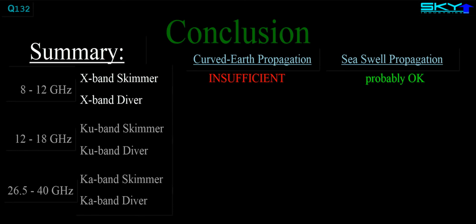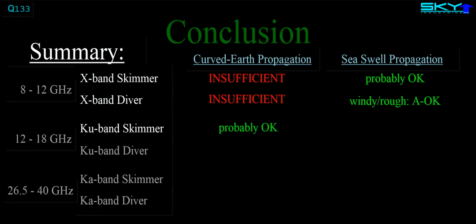If the sea is glassy and smooth, then forget it. A simple jog detector won't get you across the finish line, but if the sea surface is rough, you're good to go, most likely. KU band sea skimmer. A simple rate-based jog detector is probably okay, although the results are mixed if the sea surface isn't perfectly flat, like if there are sea swells, of which there probably are.